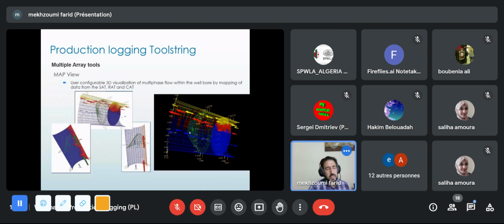Maybe you also need to estimate the viscosity downhole, but it doesn't affect much, same as the vertical one. Because PVT affects your Reynolds number, so you need PVT, and also to convert from surface to downhole and the inverse.